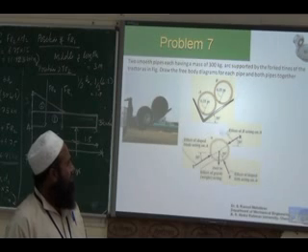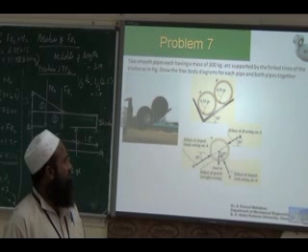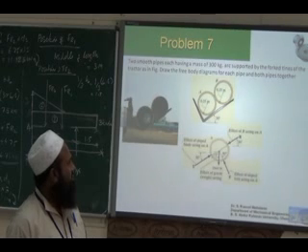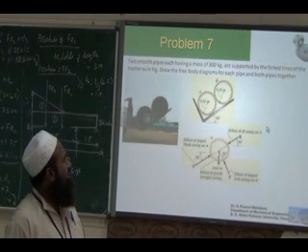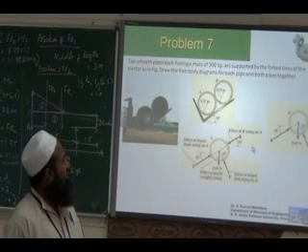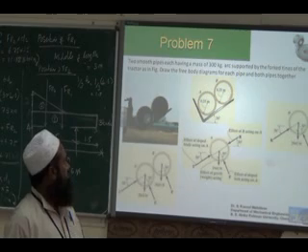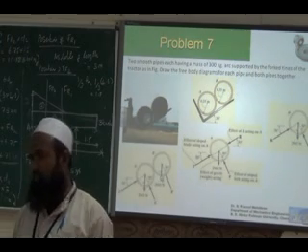So we consider only a coplanar system of forces and moment. Restriction from this surface, restriction from this surface, restriction from the other roller. So three reactions here. If you consider roller B, it will have restriction from this surface and restriction from roller A. So all together we have a system of reactions.